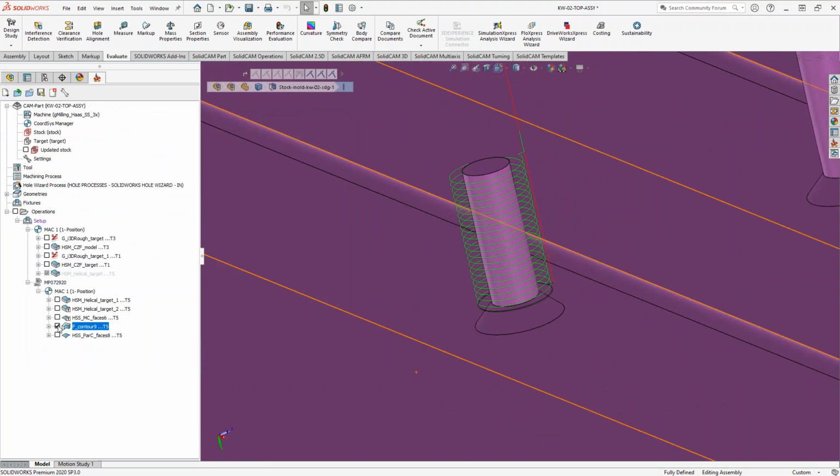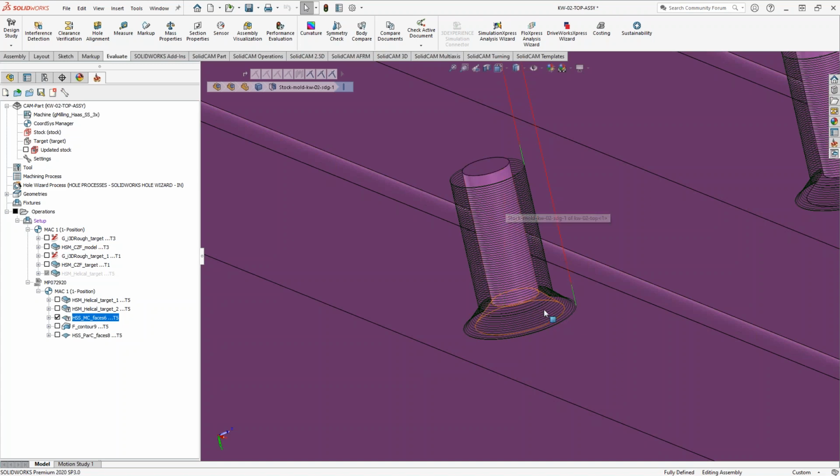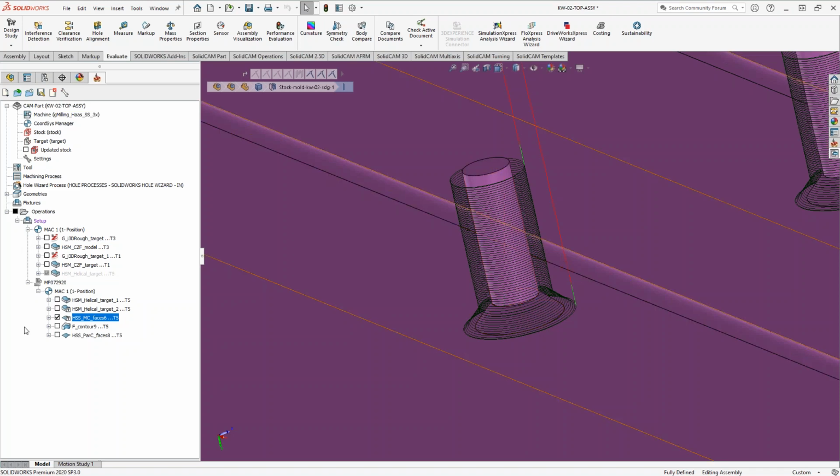And then with that previous toolpath, I could actually, with this one, if I wanted to, I could just eliminate the use of that surface, maybe just generate a toolpath just for that surface there and get my 3,000 step over on just that. And include this as maybe a gouge check surface if I wanted to. And then just do that bit there with another toolpath.